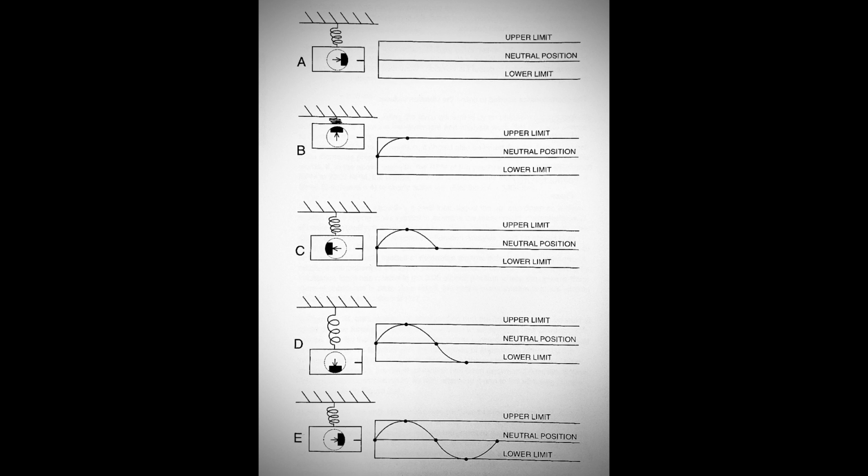So it's only going to pick up the vibration that's happening in line with the vibration measurement device. So an excitation force would be the rotation of the imbalance inside of the mass of the machine that pushes that mass up and down from its state of rest in one cycle.